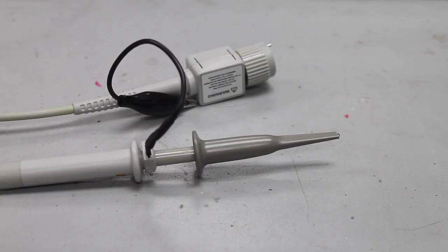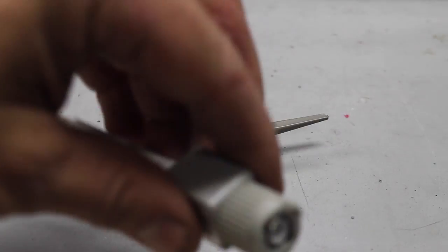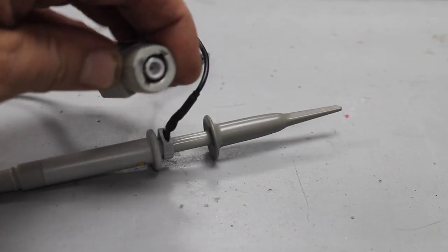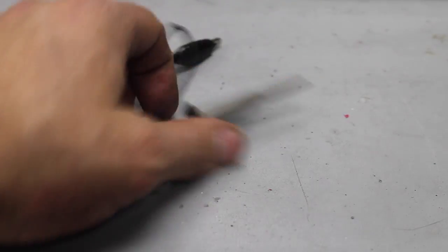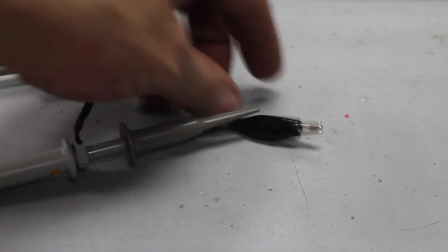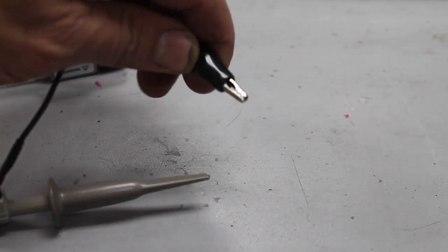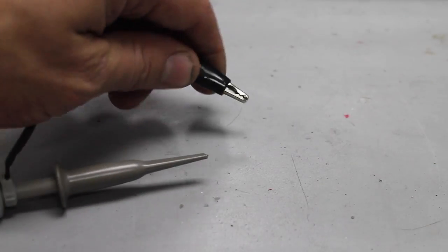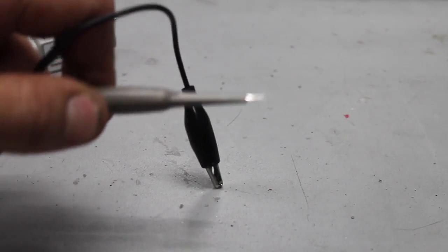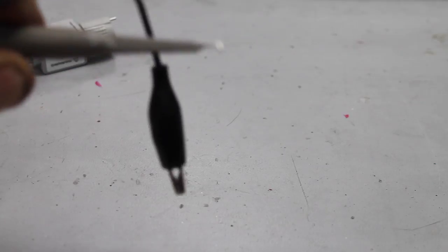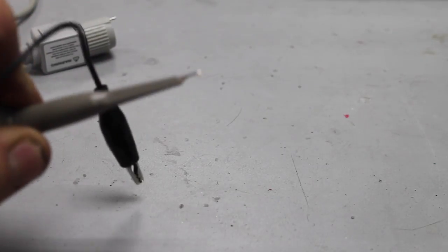This is an oscilloscope probe. This end plugs into the oscilloscope. Push it into the input port, and then twist it clockwise. This is the negative terminal of the probe. You can clamp this onto the ground of a circuit. This is the positive side terminal of a probe. Pull the shaft back to expose the probe tip. Clamp the probe onto the place in the circuit board you wish to compare to ground.